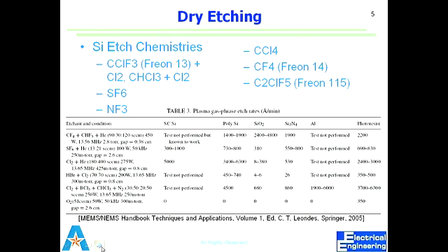What does it take for me to put a photoresist film? What do I have to do to put the photoresist film? Just spin it on there, right? So all it takes is to put it on there and spin the photoresist, and of course there are baking steps and all that. And I have to do my lithography to open this in silicon dioxide. But what I can do is leave my photoresist on after.